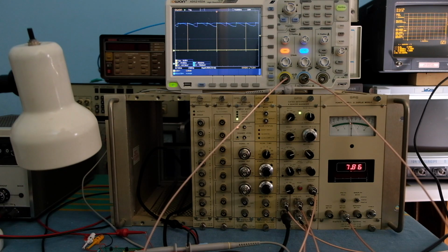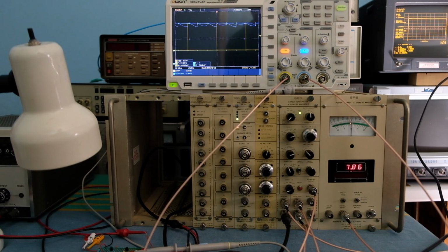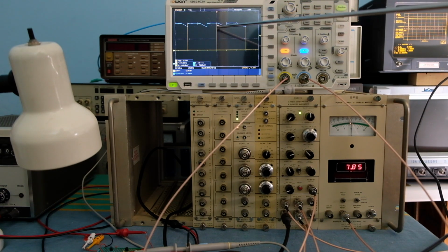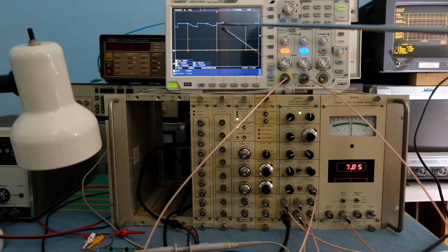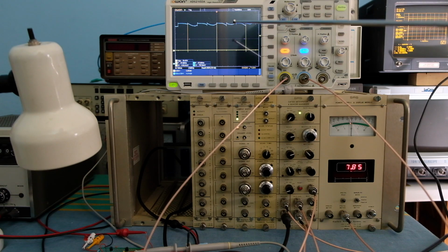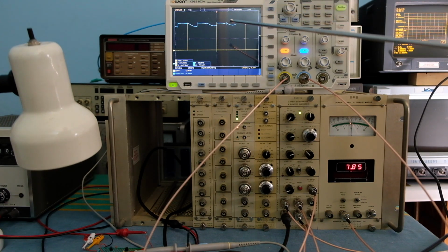So right now I'm sampling right after the reset, so it's going to measure the peak value, and you can see that on the boxcar I have 7.86 units, 7.85 units, or probably volts, if you're close to that in actual measurement terms. Right now there is very little averaging going on, an average of 3 or so, and the delay is such that I can move it back and forth around this point. If I move it to the left of the reset, it's going to measure the full amplitude of the change in the voltage across the capacitor due to the discharge by the photonic current of the LED.